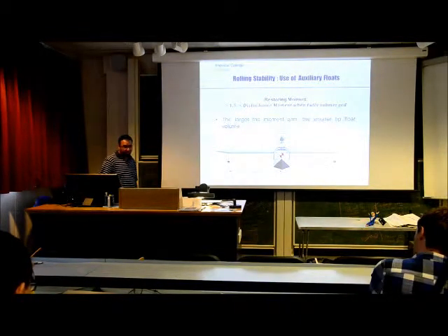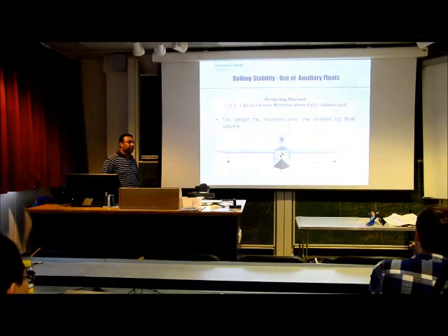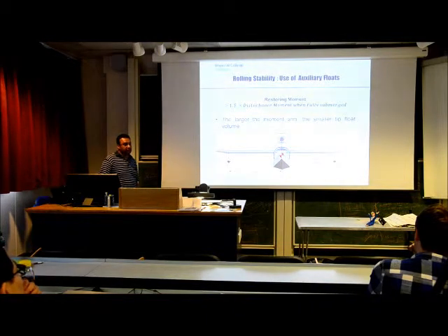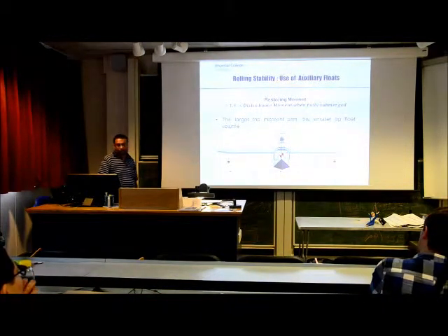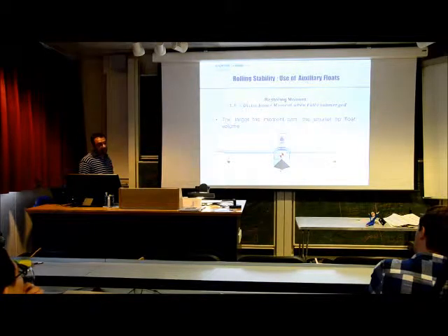It all works with the Froude number, I guess. And from there, you know approximately if you're entering the nonlinear regime and whether a linearization can give some kind of accurate prediction of stability. But I think you've got to know the speed, the Froude number you're working with first. This is generally how we do it, and then compare with what they get empirically.